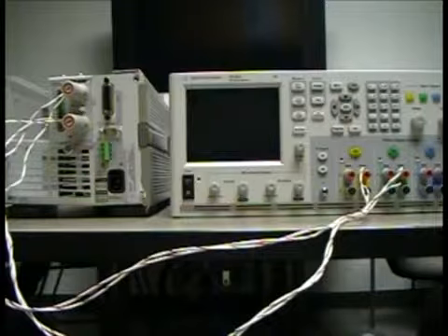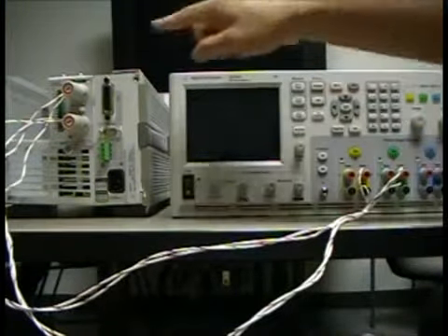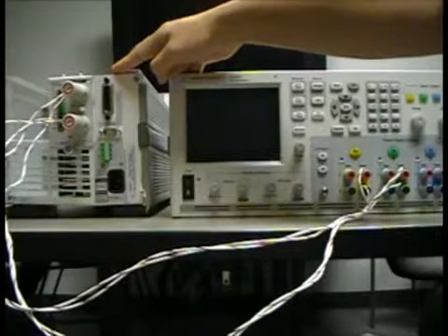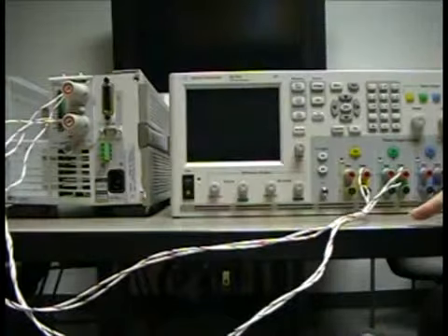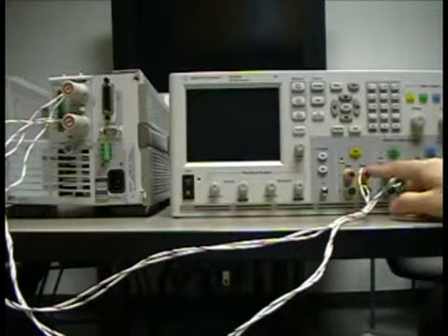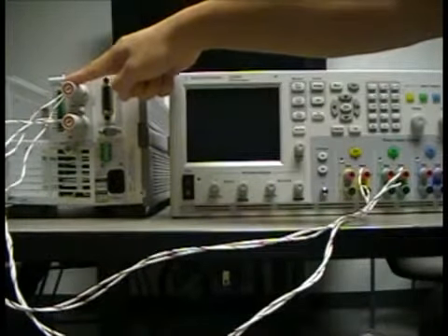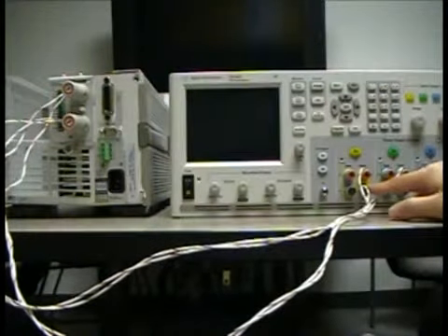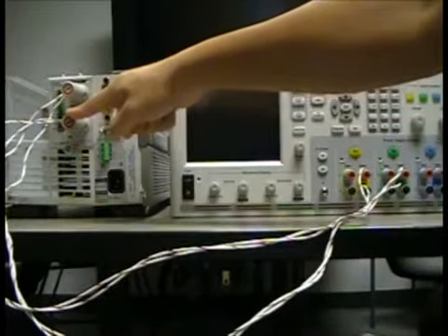In this video example, we're going to parallel output 1 and output 2 and connect them to a DUT. The DUT we're using here is the Agilent N6300 electronic load. So basically the hardware setup is just connecting the positive terminals of channels 1 and 2 to the positive input of the load. And we do the same thing for the negative terminals: the negative terminals 1 and 2 to the negative input of the load.